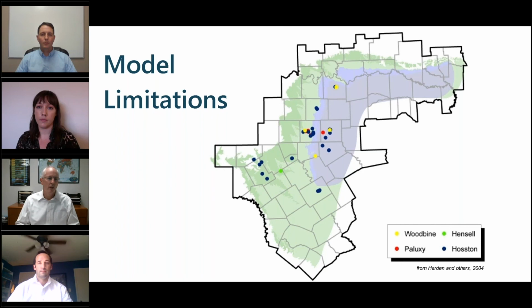Each data point may not be specifically represented if you've got 2 or more data points within a model cell. Groundwater surface water interactions are very contingent on some of the elevations you use, but if you have to use an average elevation for the topography of the cell and an average elevation for the stream stage and the stream bed elevation, that's going to limit how well those perform. So simplification basically means limitations.